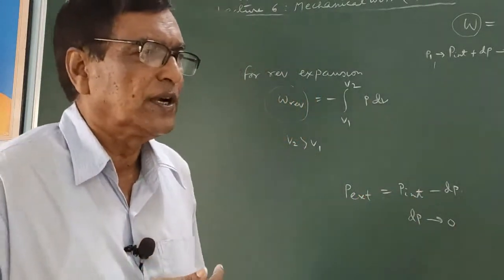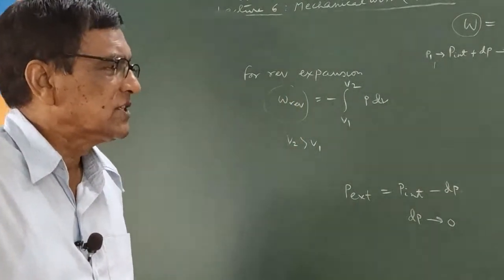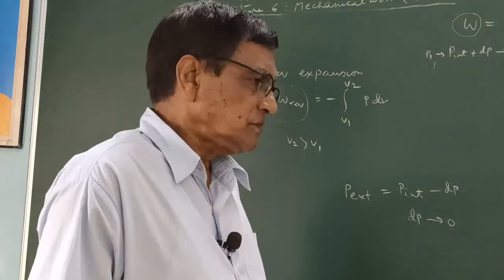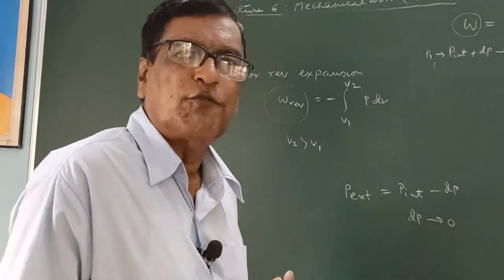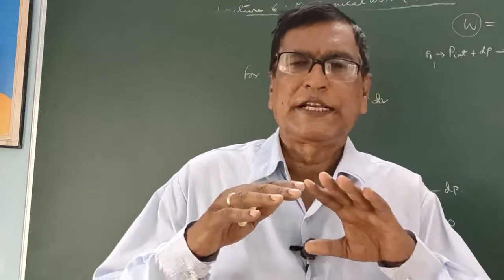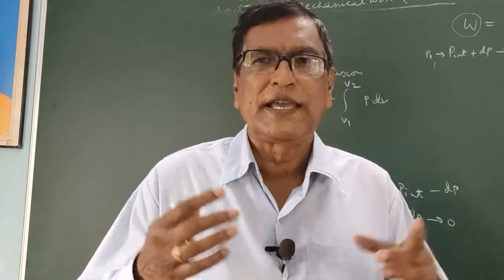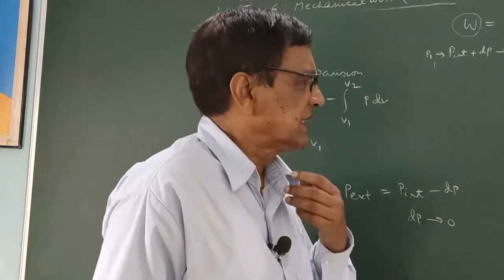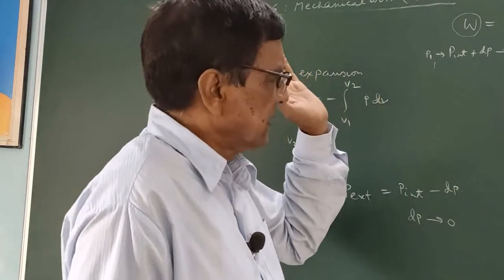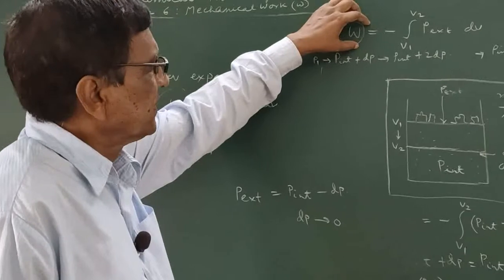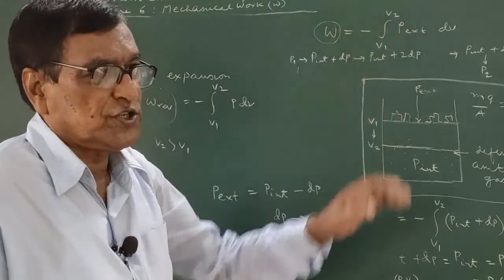So what do we learn from this reversible process? In case of a reversible process, whenever compression occurs, the minimum amount of work is required. Whenever expansion occurs, the maximum work is done by the gas. And in this case, it is also shown that the amount of work done depends on P external.